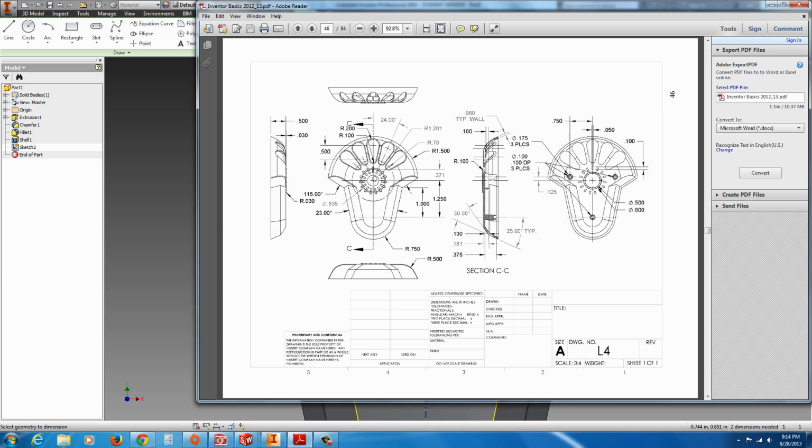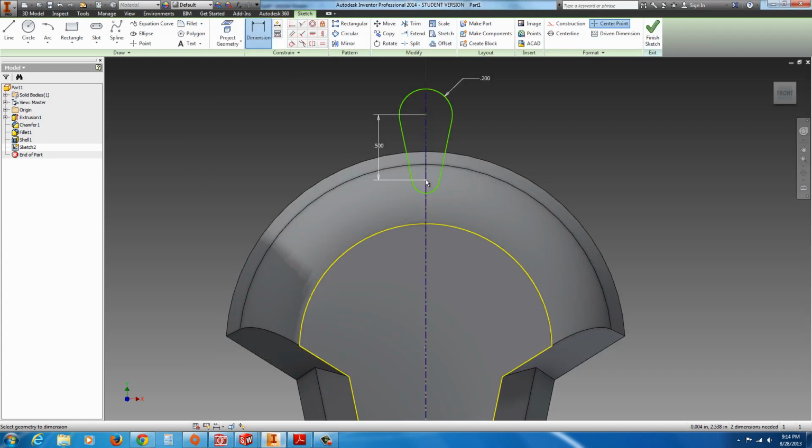In this here, we could look at this arc, and that's 0.7 from the center for the radius. Well, yes, that's correct, 0.7. So we could dimension this point. Actually, let's hit escape here and let's drag that down a bit. Get it internal there. Now we could go to dimension, from this point to this arc. That'll be 0.7 to locate it. Alright, and at that point we're ready. We could go ahead and extrude that as a cut.